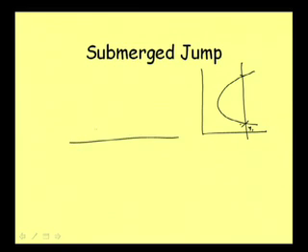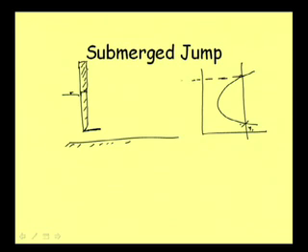Say water is flowing at this level, and maybe we are putting a sluice gate just like the case I have drawn earlier, and water may be here on this side. Its corresponding depth, the sequent depth which corresponds to this initial depth, is this one. This is y2.